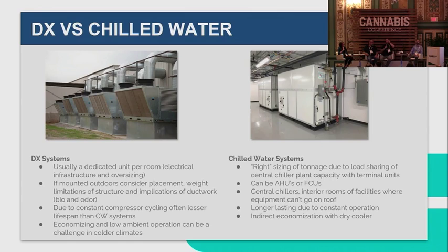And sorry to interrupt. I don't think we want to just gloss over that, it's a great point, when you're talking about the flip or load sharing. When you have a chilled water system where we are decoupled from the room directly and you are flipping rooms, you might be able to get away with less overall installed tonnage, just due to the diversity of the load, sharing the load, having the machine run. I got 50 tons in 2 rooms here and 50 tons in 2 rooms here. If I've got a dedicated machine per room, I'm buying 100 tons of machine before I even consider redundancy. You might be able, if you're on an extremely tight budget, to get away with 50 tons of chiller.